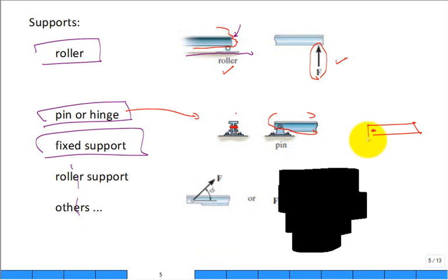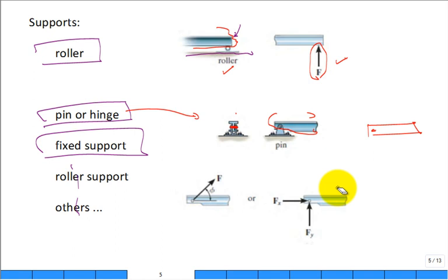Basically, this is the most common way of writing it. You would say, I'm going to have a supporting force, F in the X. Let's say if the pin broke, the beam would want to move in that direction. Then you can see there would be a push because of the pin support, assuming it's still intact, on the beam in the positive F of X direction.